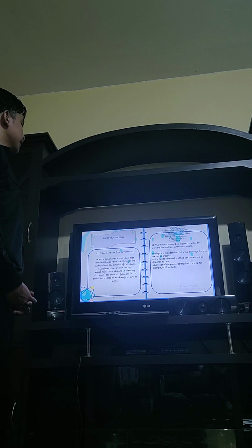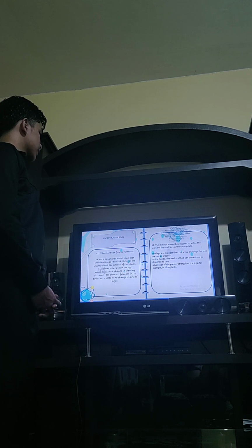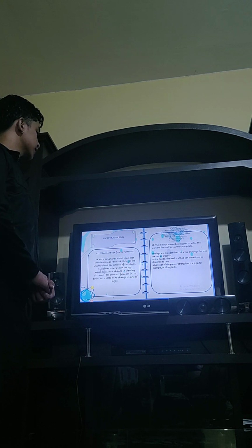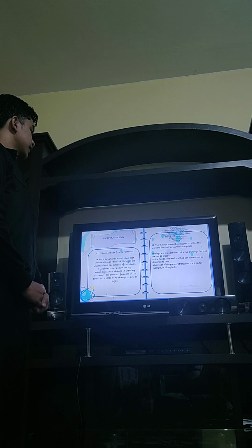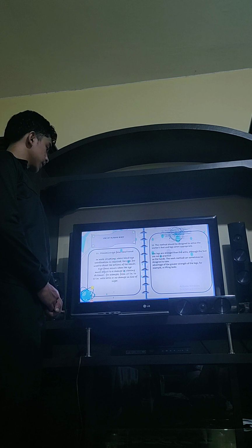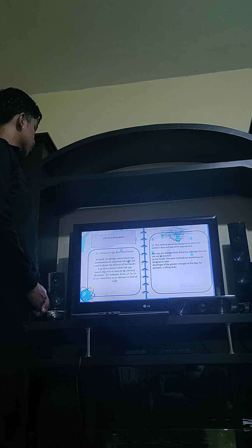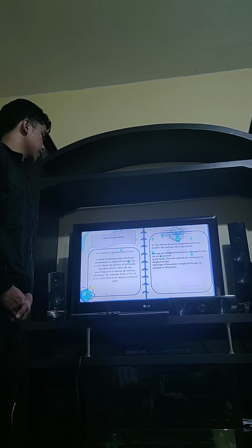Number 11. Minimize eye focus and travel. In work situations where hand-eye coordination is required, the eyes are used to direct the action of the hand. Eye focus occurs when the eye must adjust to a change in viewing distance, for example, from 25 inches to 10 inches with little or no change in line of sight.